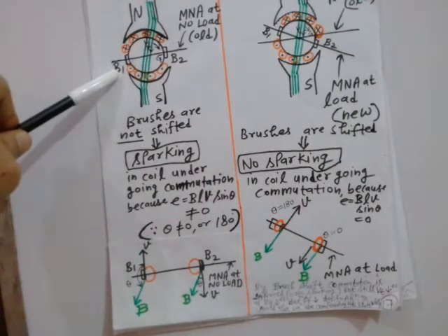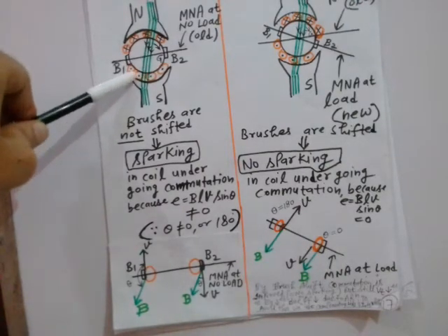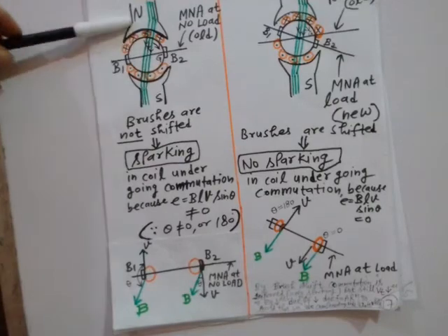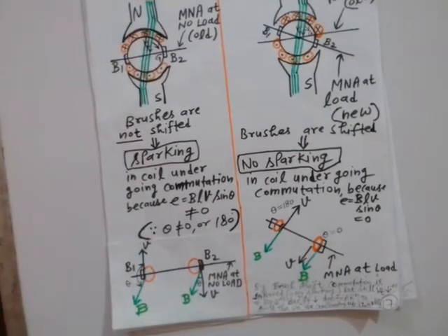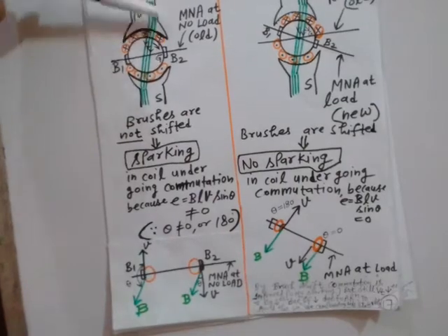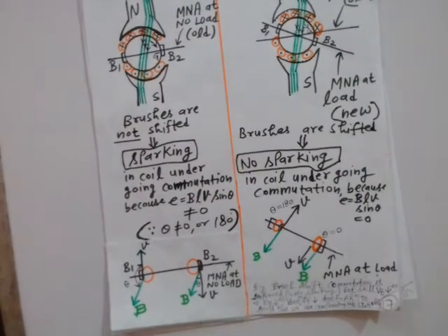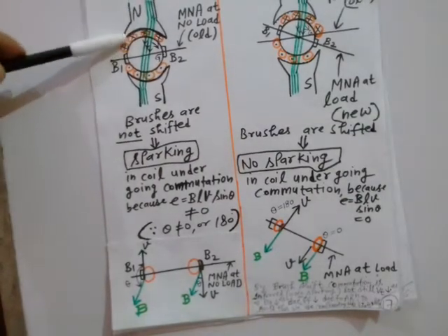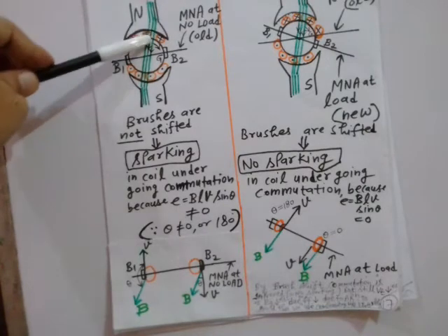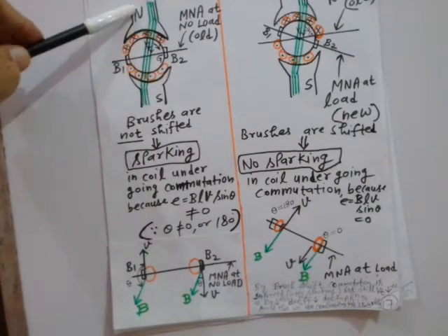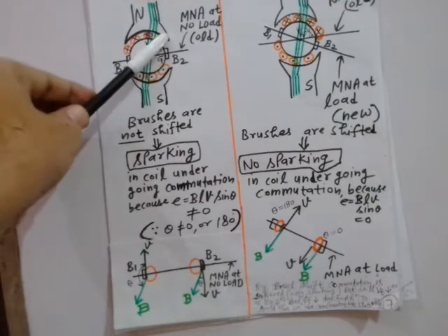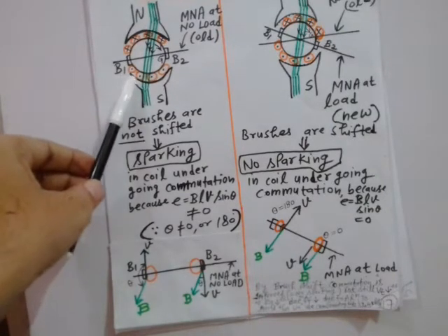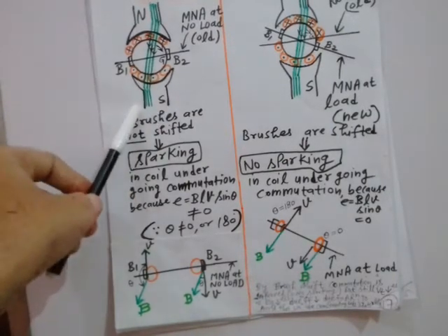So armature current IA will now flow and armature flux will be produced, and due to this the armature flux will distort these main field lines. I have already explained why these main field lines are tilted due to the effect of this armature flux. This armature flux is pushing these main field lines at the trailing pole tips in case of generator. So for north, the crowding of field lines will take place at the rightmost point, and at the leftmost point for the south pole.